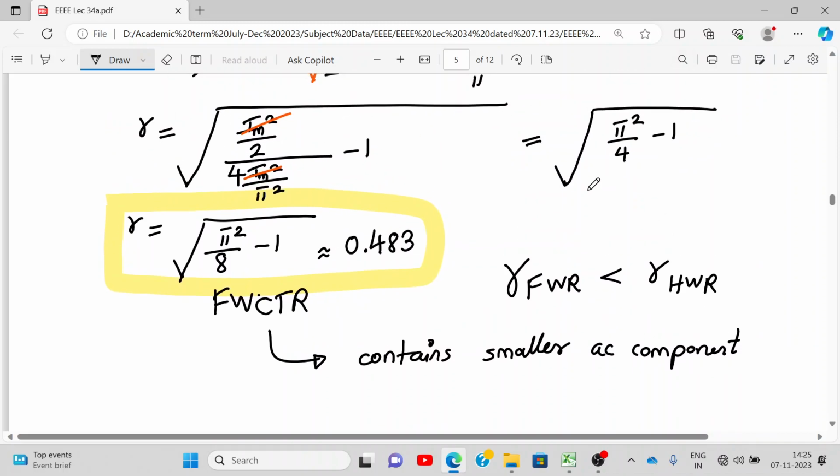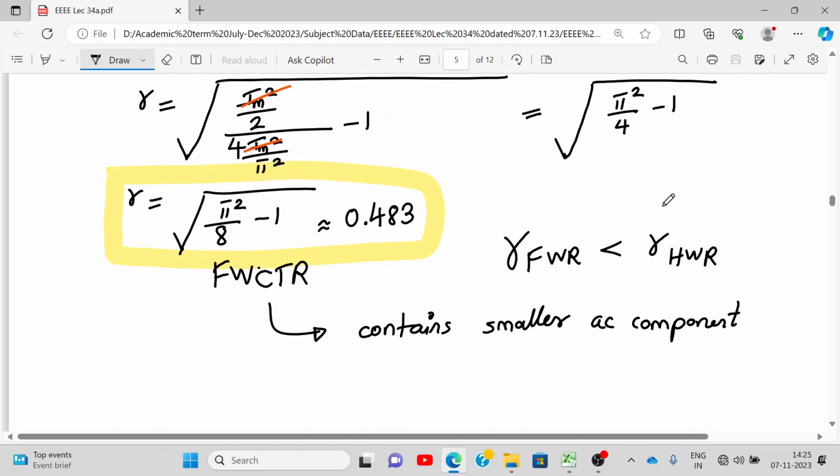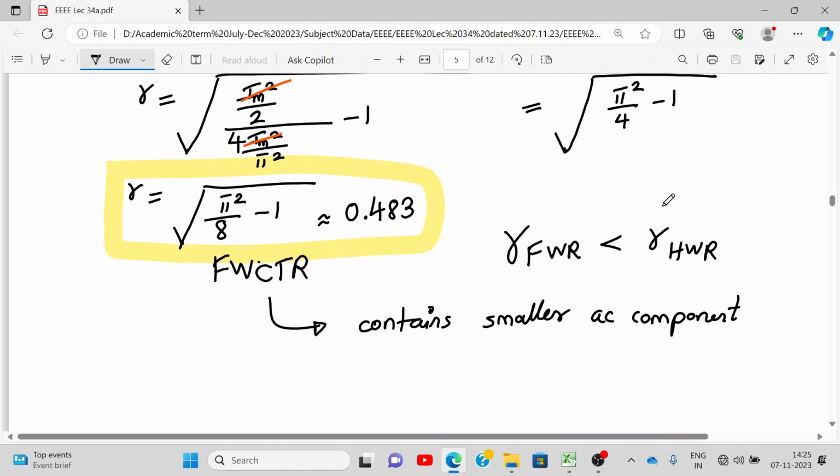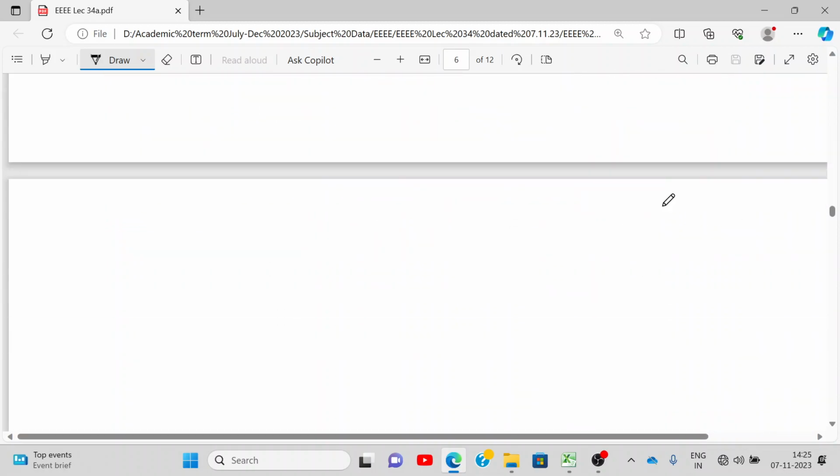I told you that the transformer utilization factor will be covered for all rectifiers together. Completed, everyone? Yes? Okay. Next I'll start with the full wave bridge rectifier. Remember, all the expressions which I have shown you right now are the same for the full wave bridge rectifier. What is the difference in the circuit diagram? It doesn't have a center tap transformer, it has a normal transformer. So on this topic, we will be discussing the circuit diagram, working and the waveforms. The analysis remains the same.